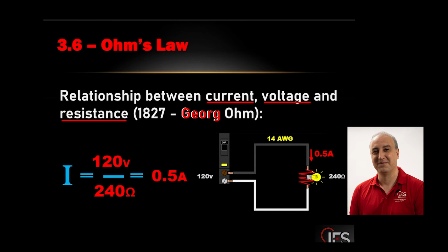The conductor size is sufficient for your load, but you cannot protect a 14 gauge with a 20 amp breaker. Always remember, there are some exceptions like ACs and motors, where the code allows us to go over. But in general circuits, your breaker cannot be bigger than the wire. It has to be sized to protect. So this is a 15 amp max wire. You have to have a 15 amp breaker, because if it's a 20 amp breaker, you can draw 18 amps on the 14 gauge wire and the breaker will not trip.